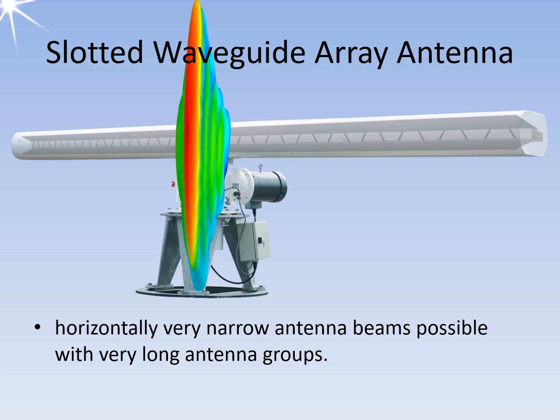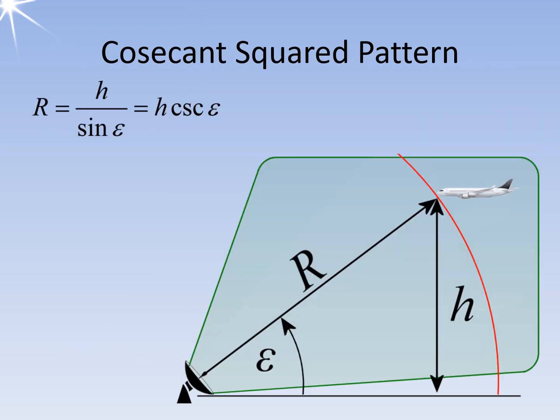By adding reflector plates above and below the waveguide, the beam can be made even narrower. With modified reflector surfaces, cosecant squared patterns can also be achieved. A cosecant squared pattern is generated with special forms of parabolic antennas or array antennas. It allows a situation-adapted radiation distribution and comes closer to the concept of ideal space scanning.